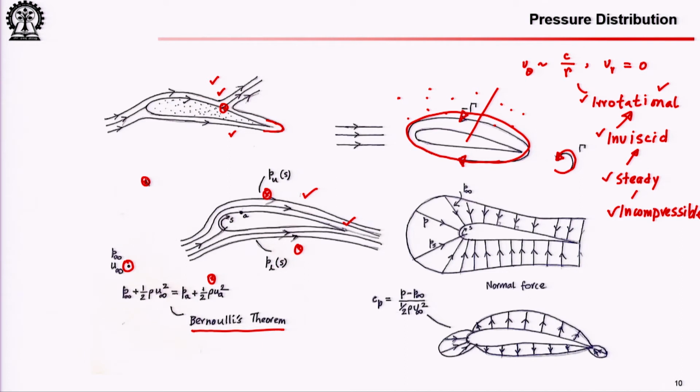But given that all these four conditions, A, B, C, D, hold, and of course the incompressible condition comes in where your flow speeds are less than Mach 0.3. Less than Mach 3 is something else; less than Mach 0.3 is where flow behaves in an incompressible manner. Same air, it is a compressible medium, maybe the compressibility is low, but it is still compressible.